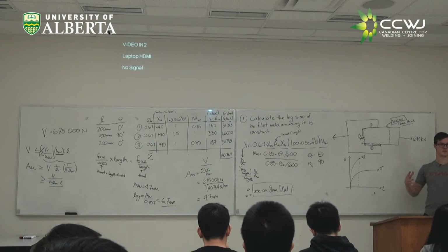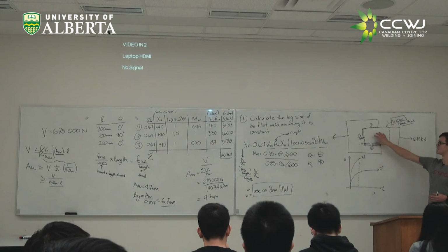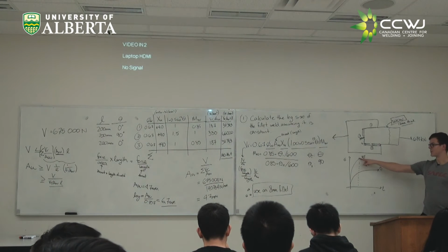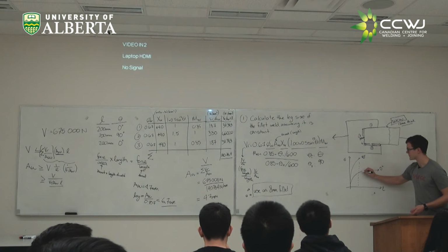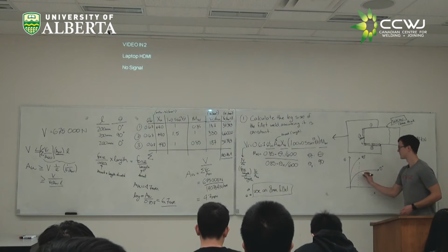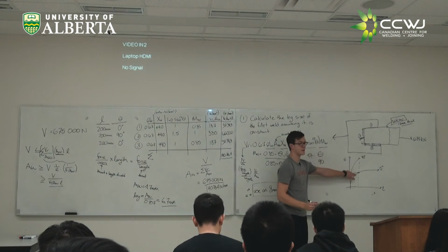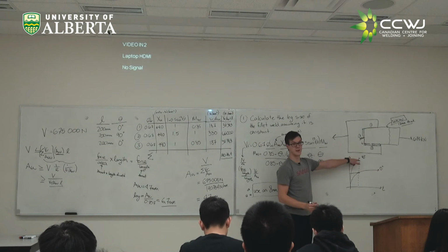It has to deform as one piece. So we're assuming that this is a rigid structure. So if the strain in our welds has to be the same across all of them, and the point where this fails is at a lower strain, this is the maximum strength that we're going to develop in our other welds before this one fails.